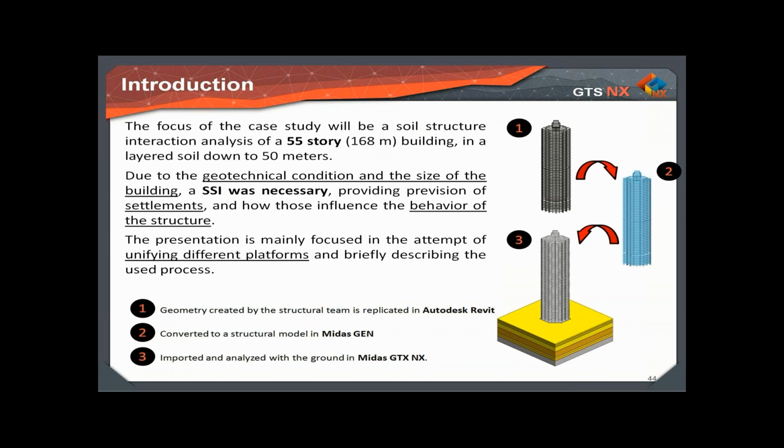So the building, which is the focus of the presentation, is a 55-story, about 168 meters tall, designed in a layered soil of low resistance. And because of the size of the building and the soil-bound site, soil structure interaction was necessary to evaluate the settlement and the behavior of the structure.